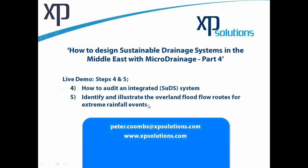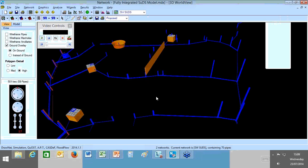So there will be 2 steps to the live demonstration. In true Blue Peter fashion, here's the one we've done earlier. So this is the network that we generated last time. We added in a range of different storage structures, and if I just click on the audio play, what I've done here, I've analyzed one particular event. It's a 50-year return period, 60-minute storm duration, and this is the consequence of that particular event. There is actually no flooding, and I can check this in a couple of ways, but I can show you the summary of the results.